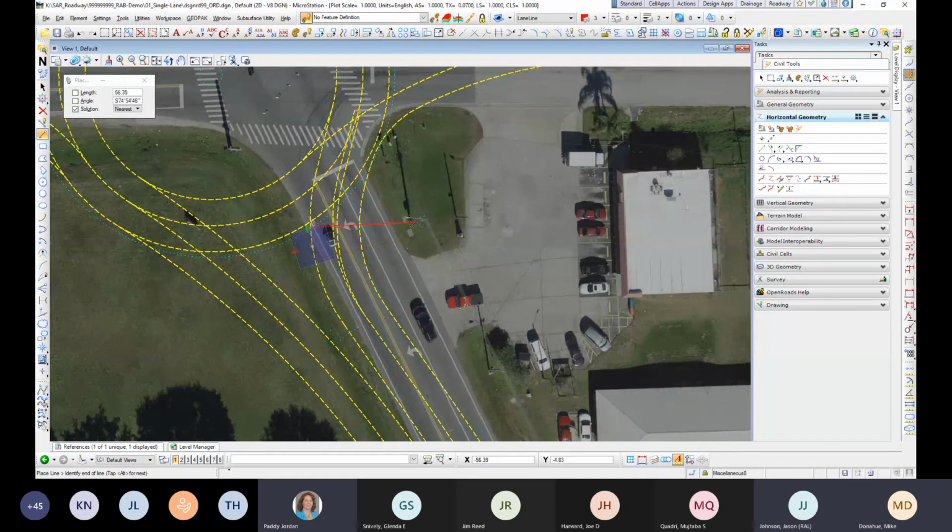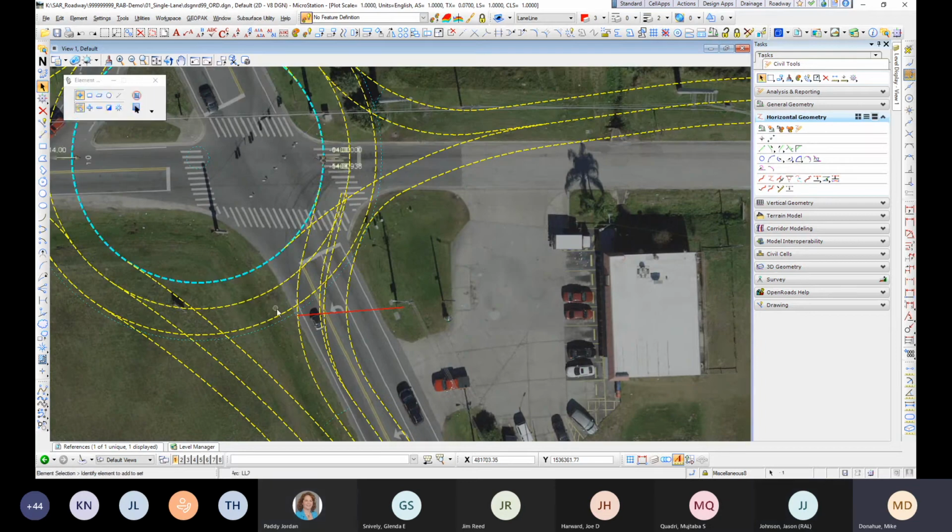I would likely have a template for the right side of my road, excluding the median, that would run along this PGL line up to this point, and it would stop. And then I would have a surface between those lines. So that void that's created in here would require its own surface. This is probably where I would begin another template on this PGL, moving to the right, to the east. So this would be a corridor. This would be a corridor. This would be a surface.